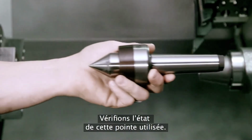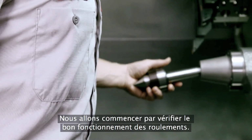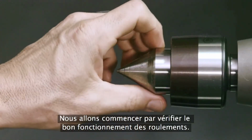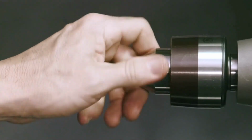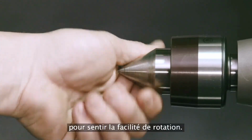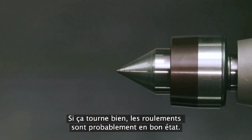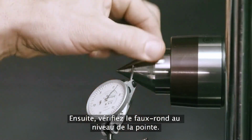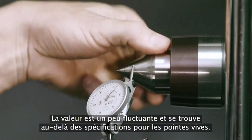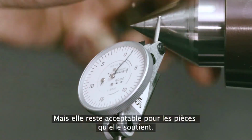Let's check the condition of this used center. First, we're going to check out how smoothly the bearings roll. Rotate the tip 4 revolutions, and then keep rotating in that same direction, feeling for smoothness of rotation. If it's smooth, the bearings are likely in good condition. Next, let's check the runout at the tip. The reading is a little jumpy and it's above this live center's specifications, but it's still acceptable for the parts